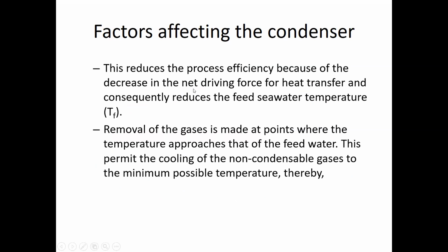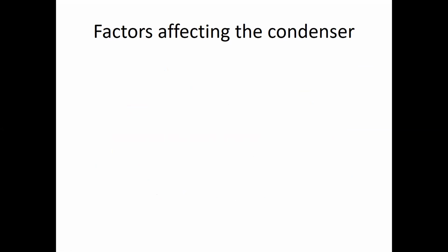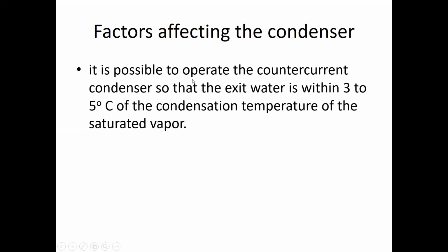Here we're talking about these gases. We started with a temperature difference that happens for the vapor as it leaves the evaporator and goes to the condenser, losing some of the energy, which definitely reduces the system performance. In the condenser, normally, we expect that it would operate at a counter current arrangement, and there's a temperature difference between the feed water that leaves the condenser and the saturation temperature at which it will be heated in the evaporator in the order of 5 degrees centigrade.